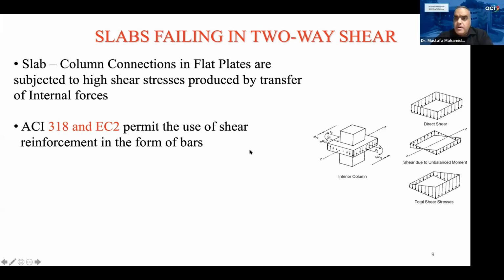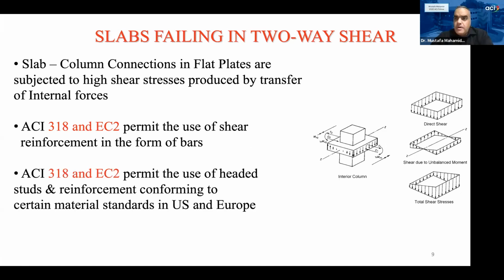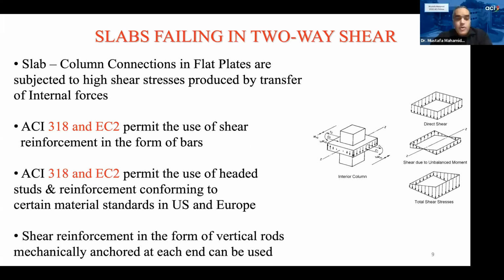Both ACI 318 and Eurocode 2 permit the use of headed studs and reinforcement conforming to certain standards, whether in the US or in Europe, following what's stated in 318 and EC2. Shear reinforcement in the form of vertical rods, mechanically anchored at each end, can be used. So whether it's that